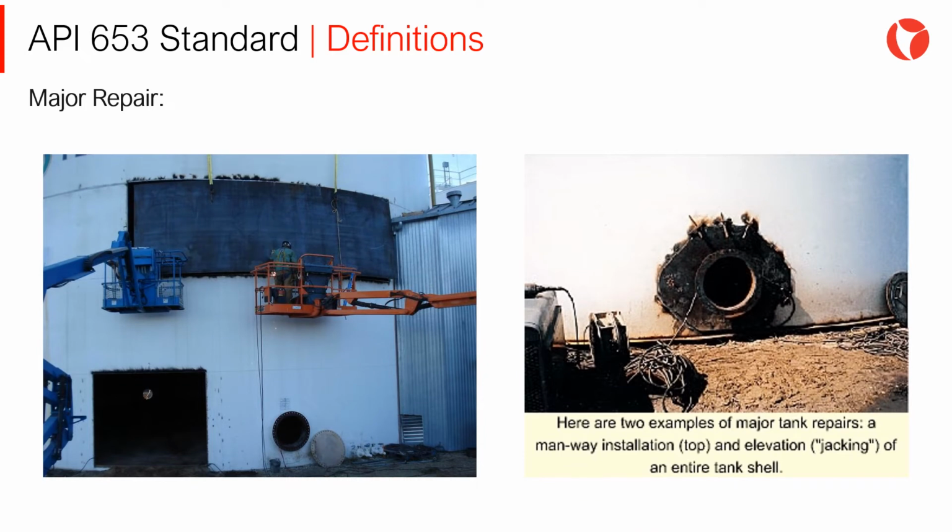Two examples of major repairs can be seen on the screen now. On the left, we can see a shell plate, a complete plate, being replaced, and on the right, we can see a manway being installed near the shell-to-bottom joint of the tank.